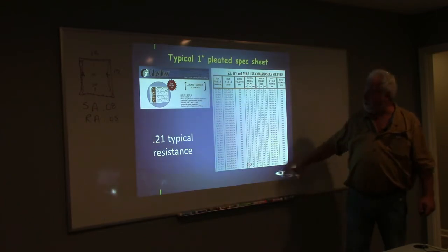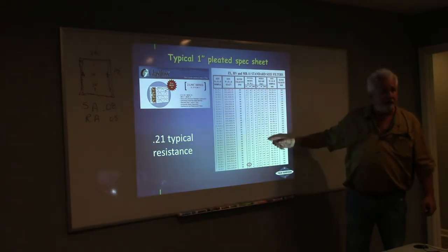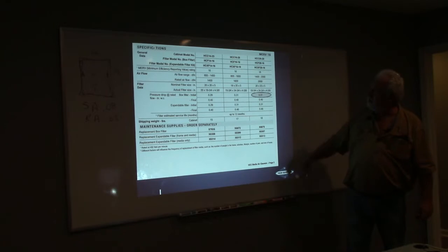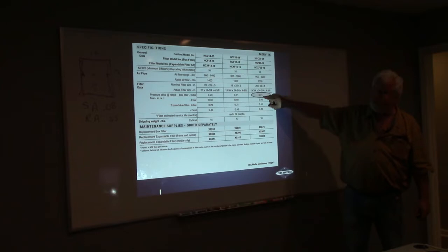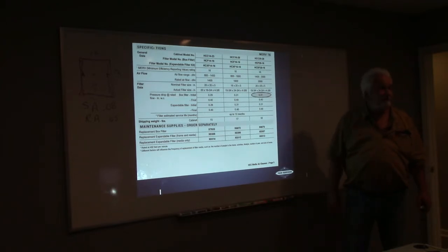All right, so depending on the filter we're putting in there, we're going to have to put that all in. So here's a MERV 16. Look at this filter. What kind of resistance do I have on that? 0.31. How restrictive is that filter? Pretty restrictive, is that right? Remember, how much did we have total that we could work with? Remember we said 0.5.